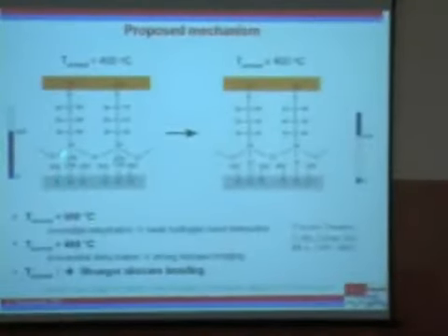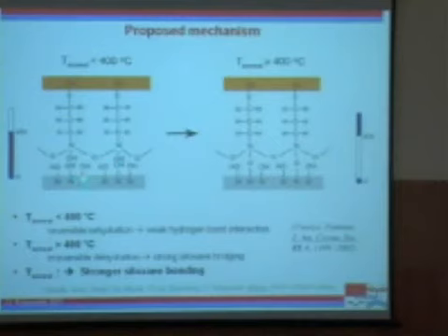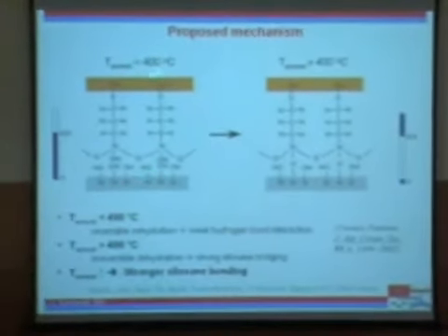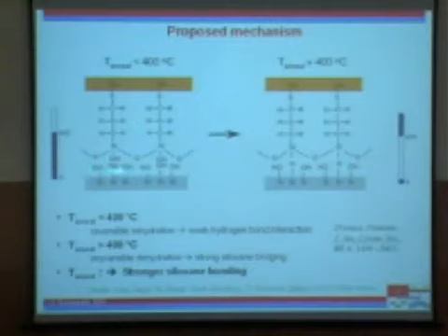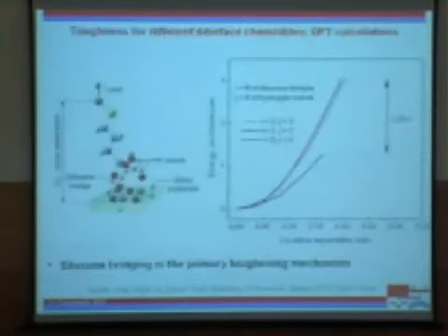Okay, so the bonds formed here are reversible below 400 degrees centigrade. So this remains a weak link. And over here, though, at higher temperatures, the bonds that are formed stay put, and they are stable, and they do not revert to the SiOH bonds, and hence you have a case where both the interfaces are strengthened remarkably.